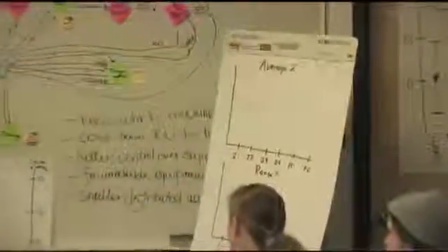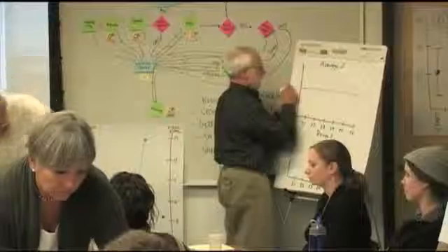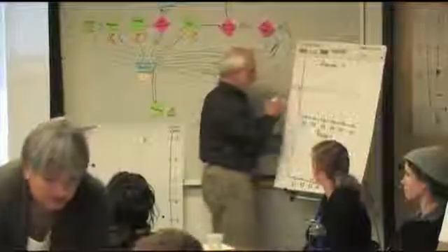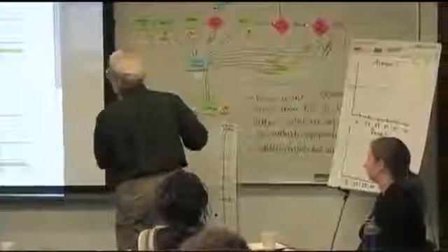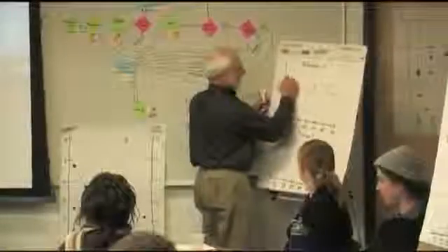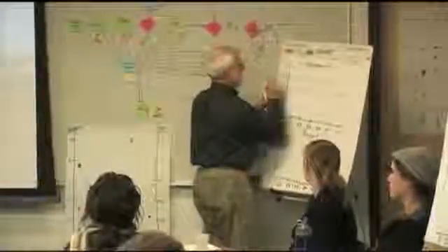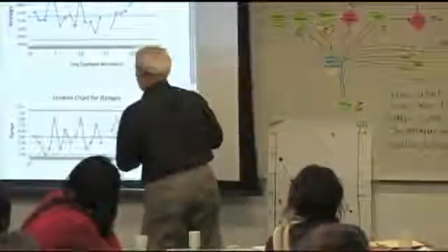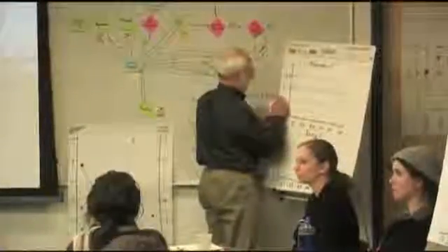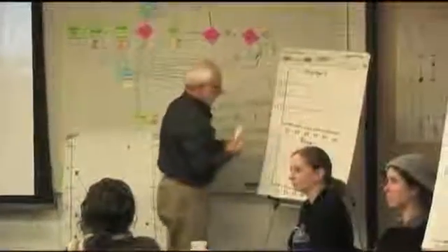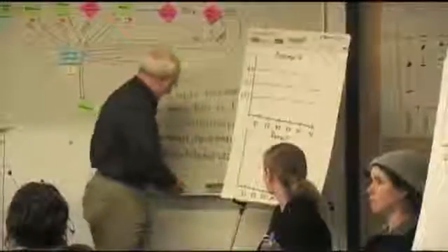So we want to do something like this. First of all, let's get the mean. I'll just do one, and I'll let the other tables do theirs. So this is like 72.5. That's the mean. And then the upper control limit is about 75.4. So we'll just put that here. And the lower control limit is 69.5. So, okay, you're going to want to finish that. This is for the average and this is for the range. And I'll let each team finish their own.